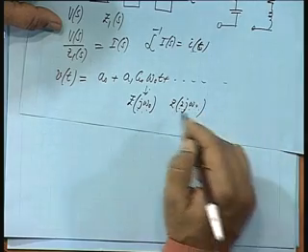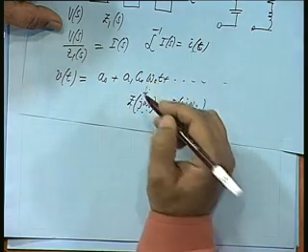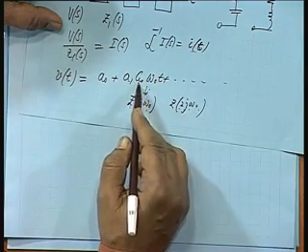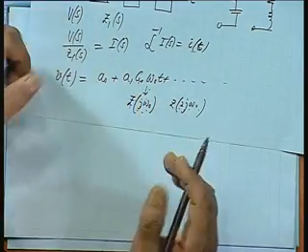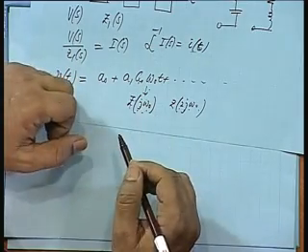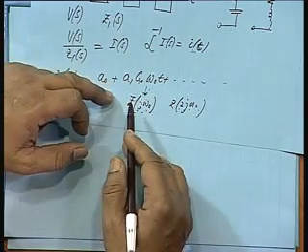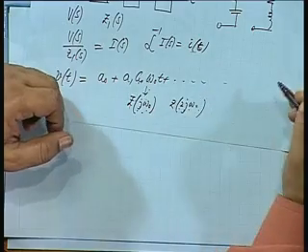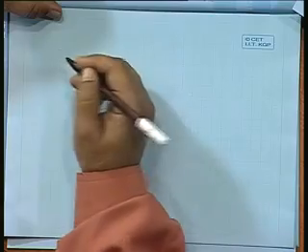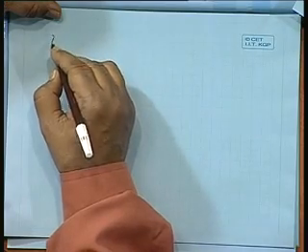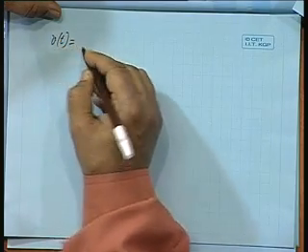Okay. For different frequencies at j omega naught, 2 j omega naught, 3 j omega naught, etc. We calculate the complex impedance. Once you know the complex impedance, the voltage component divided by the corresponding impedance gives you the component of current at that frequency. So, now we can apply superposition theorem, take all the currents together and then we can add them together. Okay.